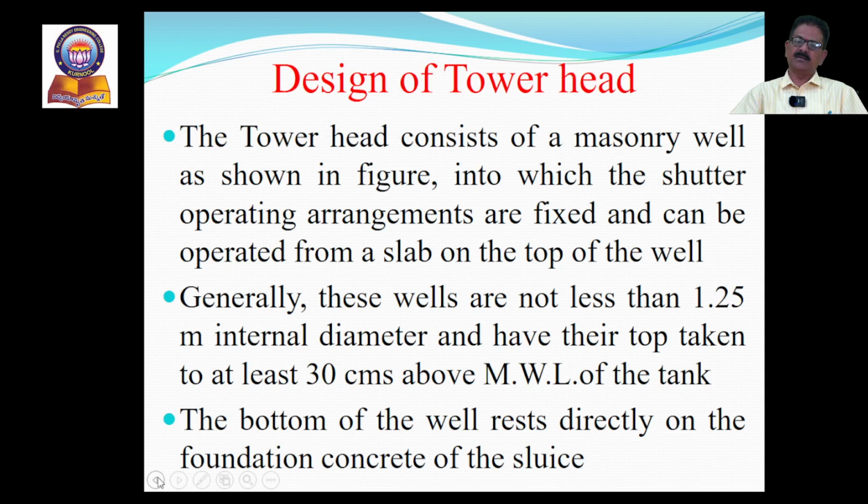We can see the position of this tower head in the plan also, as it is at the entrance of the sluice barrel. In the previous topic we discussed the design of the sluice barrel, for which we fixed the level of the foundation concrete. Therefore the bottom of this tower head simply rests directly on the foundation concrete of the sluice barrel.